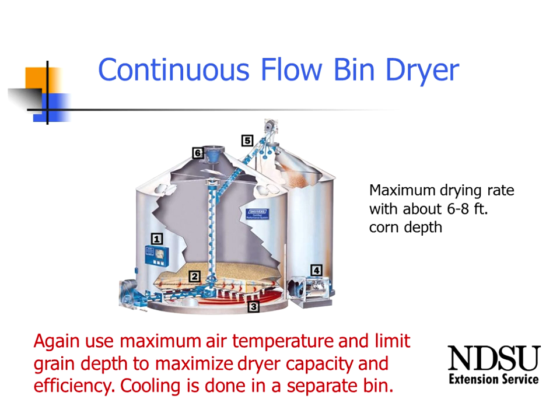And it just really emphasizes that we're really looking at two things when we start talking about energy efficiency with any of these drying systems. It's the design portion and then the management or operation application of that dryer. Particularly in these dryers, if we're backing off on the air temperature or doing other things that increase the energy efficiency, we will very quickly find out, even though we have the depth being such that we would expect good performance, because of the management, we may not get the expected performance out of that dryer.